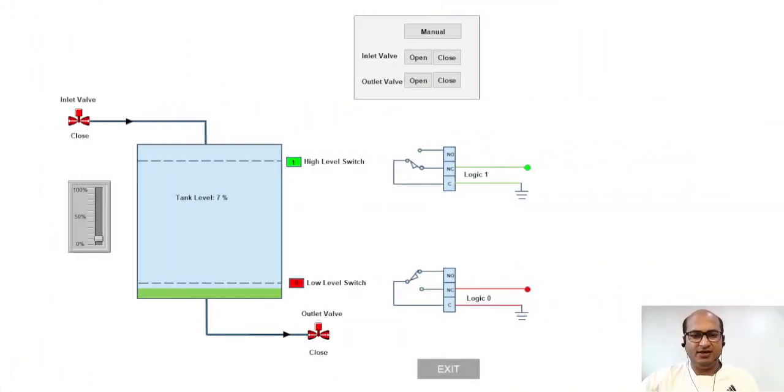See, again we'll see on the HMI. This is in manual mode. I think we have set this logic bit to 1, that's why it is not giving the output. Yeah, so let me first make it 0. Okay, in the PLC the close bit was set to 1, that's why it is not giving the desired output. Now I make it 0. So now we'll check, it is open. Now if we want to make the output open, it is open, you can make it close.